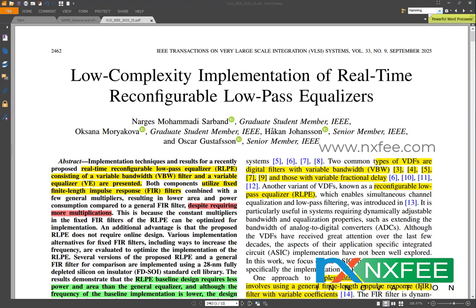The novelty of this proposed work lies in optimized arithmetic reformulation that reduces the number of adders and flip-flops, leading to lower power consumption, reduced complexity and improved timing performance. The complete design is described in Verilog HDL, functionality verified using ModelSim, synthesized, and performance comparisons are carried out using a Xilinx 7-series FPGA platform.